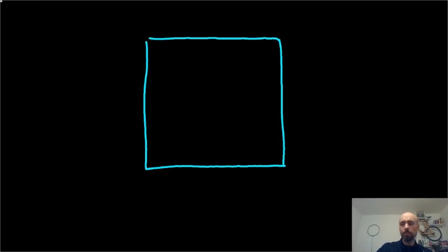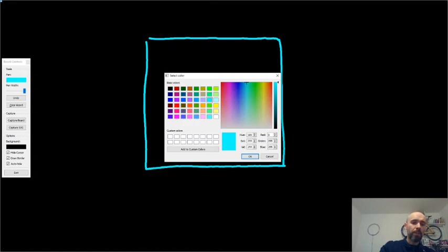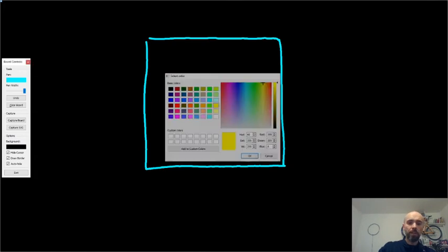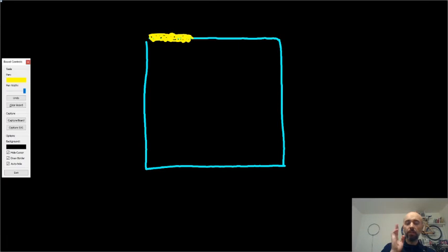Now, if we zoom in, when you laser cut this line, what happens is that you're burning away a certain amount of material, maybe not that much, a few tenths of a millimeter, but the cut is not going to be a single line like a cut made with a blade. We are burning away material.